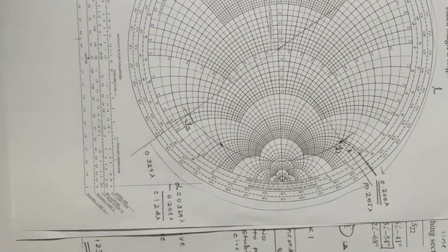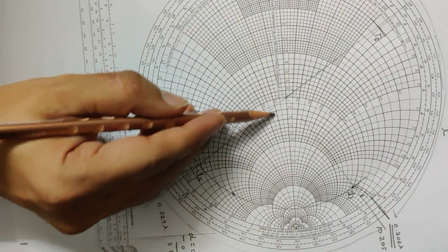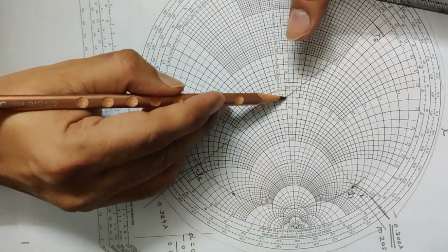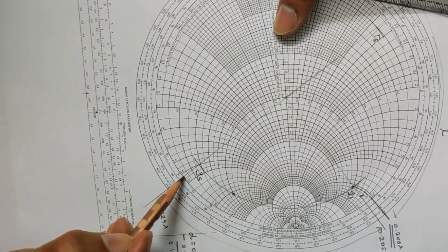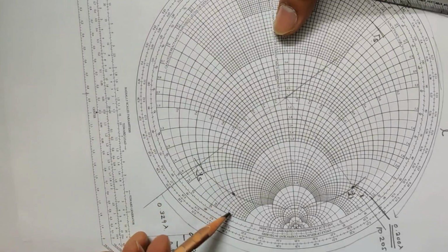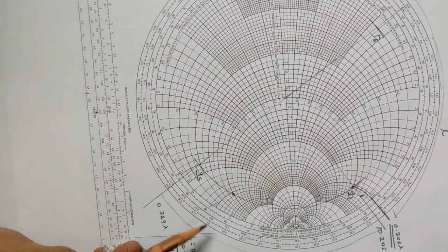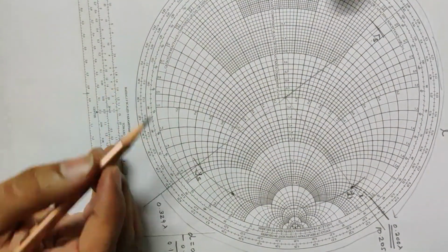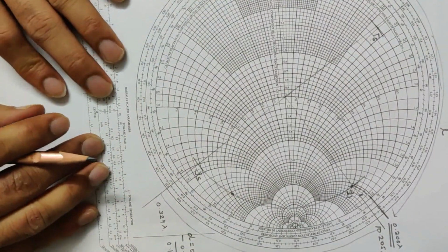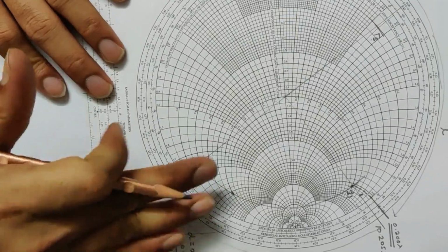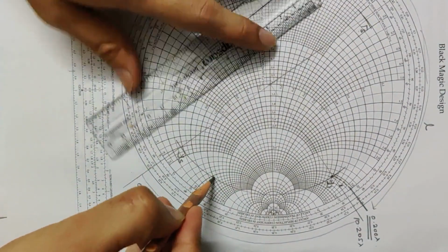If we select the lower point for the matching purpose, then one has to draw a line from the center of the Smith chart to this Y2 point and extend it on the wavelength scale. In that case, the distance of the stub will get reduced, but the overall length of the stub will get increased. So depending upon the requirement, you can select the appropriate design. Now here again I will show the second possible design for the matching of gamma S using the same Smith chart. So if I extend this thing,